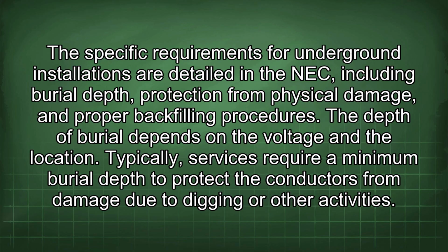Specific requirements for underground installations are detailed in the NEC, including burial depth, protection from physical damage, and proper backfilling procedures. The depth of burial depends on the voltage and the location. Typically, services require a minimum burial depth to protect the conductors from damage due to digging or other activities.